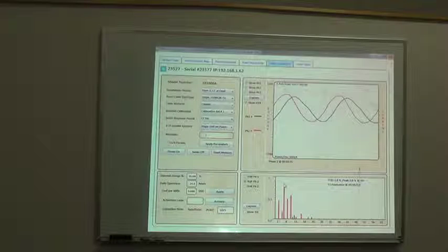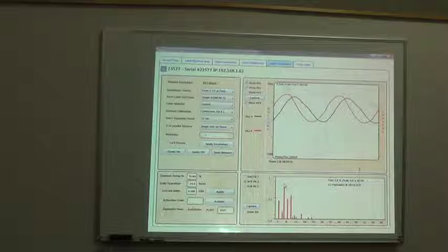Right. First of all, they're expensive. Secondly, you have to shut down the power. First of all, you have to identify where they're coming from. Even if you do identify it, now you have to find out exactly what harmonic filter to buy for it. So you have to make a decision. It's much more expensive, and you have to shut the power off while you're doing it, okay? Because they go in series with it.